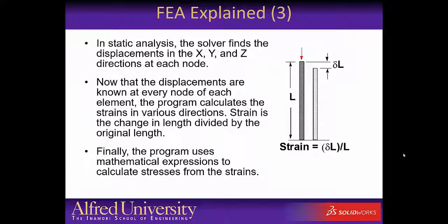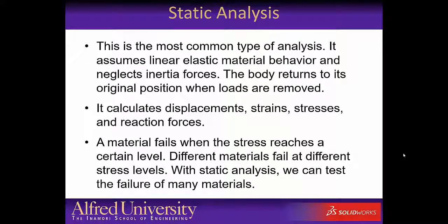Once the strains have been determined, the program can use mathematical expressions to relate these to stresses. You can think about the stress as a normalized force. More on that in a moment. We'll be performing what is called static analysis in SOLIDWORKS. This is the most common type of analysis. It assumes what's called linear elastic material behavior. It neglects inertial forces. The body returns to its original position once loads have been removed.